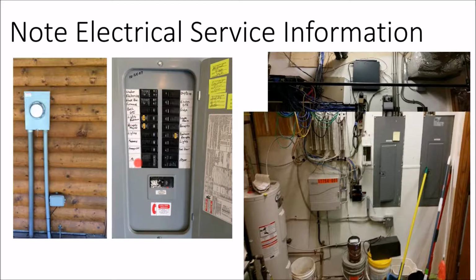What this service panel picture tells me is two things. I can zoom in on it and get the rating of this breaker, which turned out to be 200 amps, which is pretty common. And this is a bottom fed, so it's probably coming up from underground into this breaker here. So we get that it's a 200 amp service panel. We can also see if there's space for a line side connection or for a load side connection. It doesn't look like there's space for a load side.